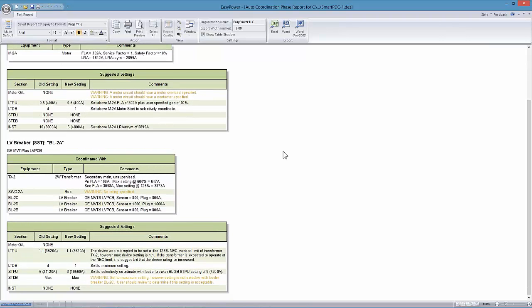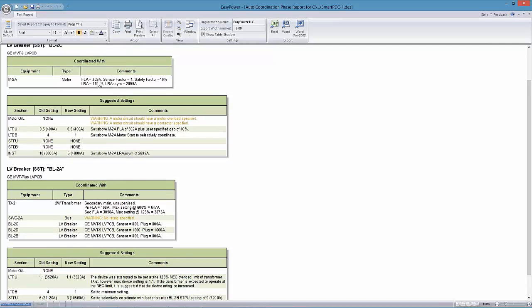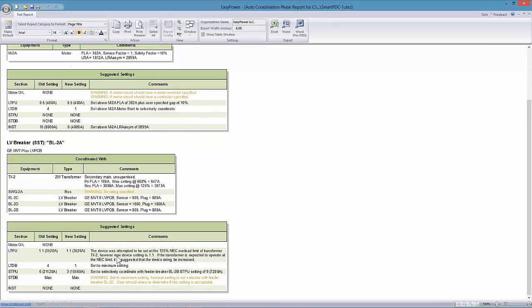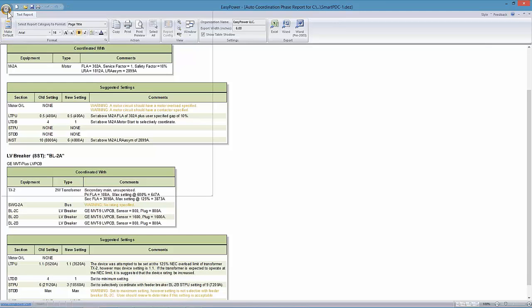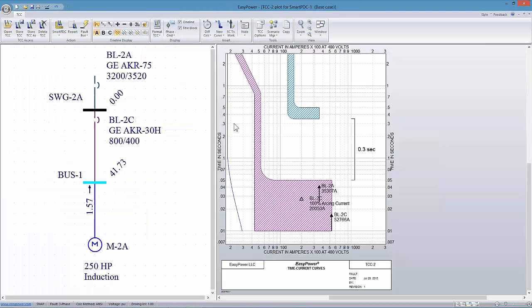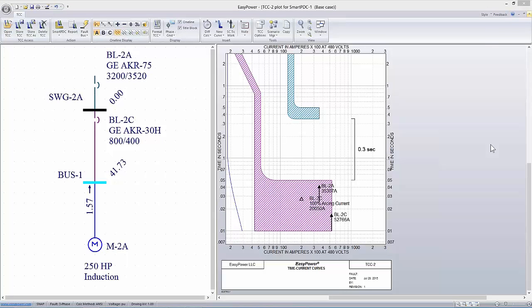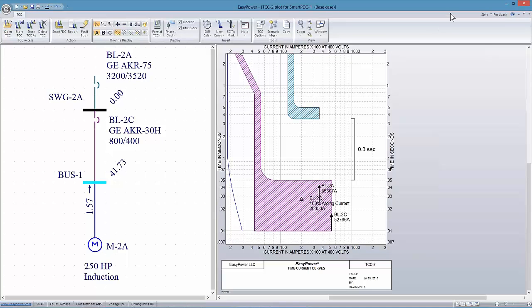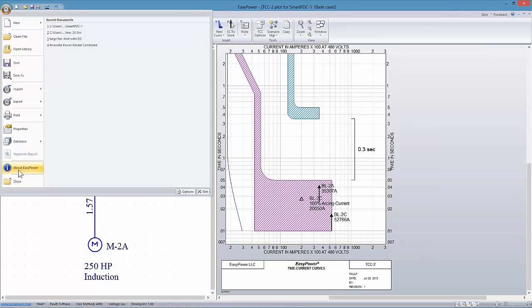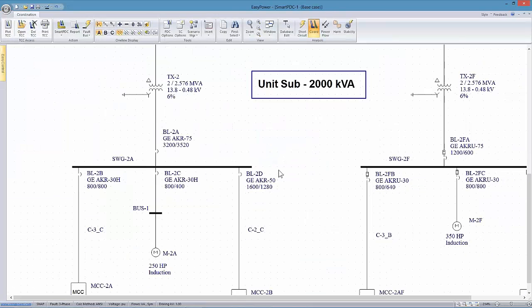So very simply, the system could be looked at as doing a first pass auto coordination, and then the engineer reviewing what the recommendations are and applying most productive time to resolving the errors or warnings that the tool indicates, rather than going through the whole process for every breaker in the system. Obviously, you want to check every breaker, but at the same time, having the tool go through the initial steps for you would give you specific verification that that's the place.